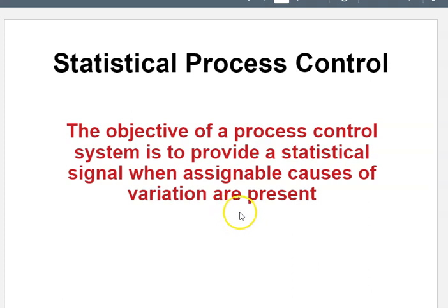So our long-term goal is to observe the system and make sure we create an upper bound and lower bound for our process variation, and if everything is in control, then all those values will be between the upper bound and lower bound. If anything goes wrong, those will be higher or lower than the upper bound and lower bound.